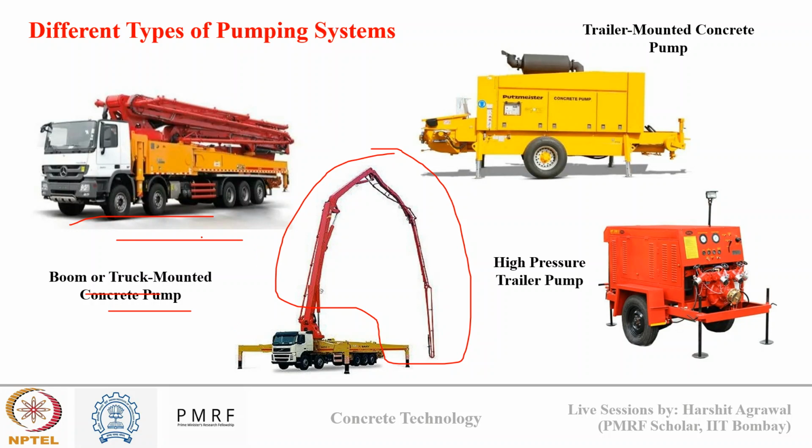And the best part of such a concrete pump is that it is remote controlled, so it is safe, faster, and less labor intensive than manual pouring. Plus, since the truck can also be moved around, it is easy to pump concrete to all the locations. So you can see in the drawing also, we have a truck here, we have a boom section, and we have a pipeline through which we can easily pour concrete to any site in a high rise building also.